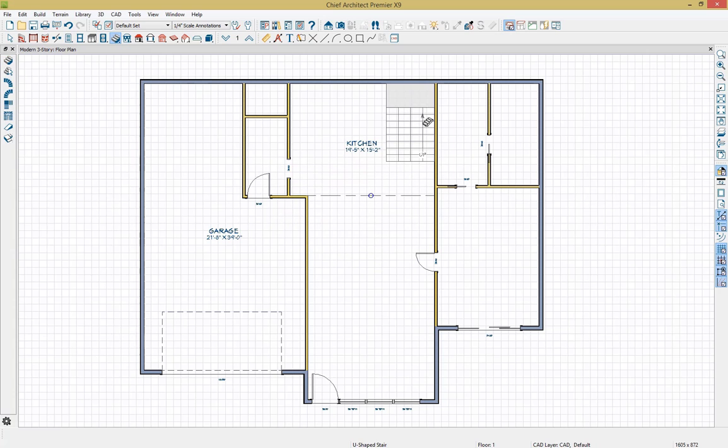And we'll bring our cursor into our plan. If you bring it over towards the wall, the up will switch over to this right hand side, or you can bring it over to the left hand side. If you bring your cursor even further and go to this wall, it'll change the orientation. So it gives you a lot of different flexibility on how that's running. And then we'll just click once we're happy.